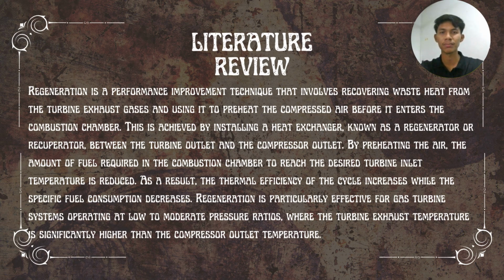This is achieved by installing a heat exchanger, known as a regenerator or recuperator, between the turbine outlet and the compressor outlet. By preheating the air, the amount of fuel required in the combustion chamber to reach the desired turbine inlet temperature is reduced. As a result, the thermal efficiency of the cycle increases while the specific fuel consumption decreases.